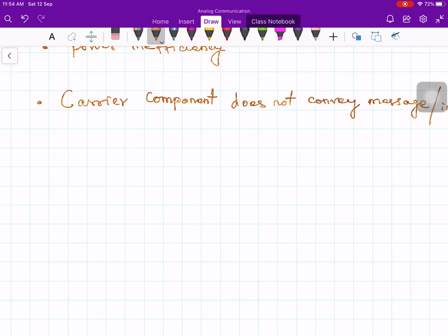One possible answer is the design of a demodulator, which is extremely simple in this case, which does not even require us to do a synchronous demodulation. So there is no need to generate the carrier at the receiver, no phase synchronization, no frequency synchronization, nothing. A very simple, extremely simple demodulator. But in the case of DSBSC, the demodulator is not very simple, it is complex. So for that reason, we go for this AM modulation with carrier.